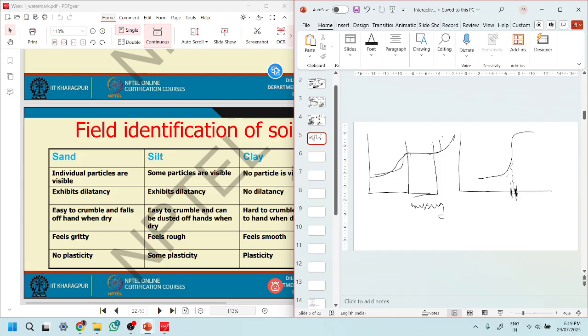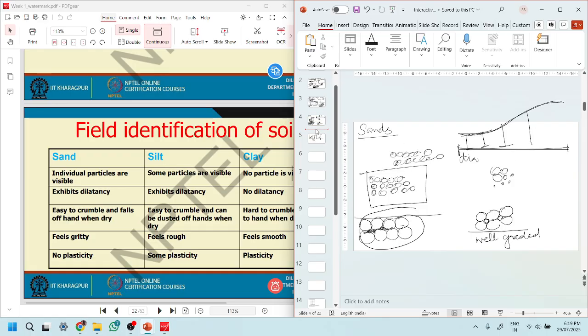In these kinds of soils, their properties differ from well-graded soil properties. And why is that? Because everything boils down to the nature of the soil, what kind of structure the soil skeleton is forming, and based on that, its permeability, its void ratio, its strength characteristics, all of this will be affected.